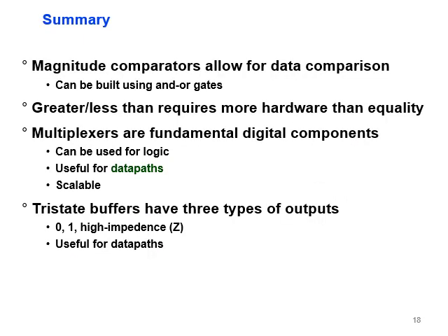Let me summarize. In this topic, we discussed two things, magnitude comparator and multiplexer. For the magnitude comparator, we compare numbers to see if they are equal, greater than, or lower than. We discussed different situations, and we wrote the truth table and the expression, and then we moved to the multiplexer, which is a data selector. It's like selecting a switch, where we use a 4-to-1 selector and an 8-to-1 selector and combinational selector, or let me call it simply mux, and we saw how it worked. Let me stop at this point, and we continue in the next topic. See you.